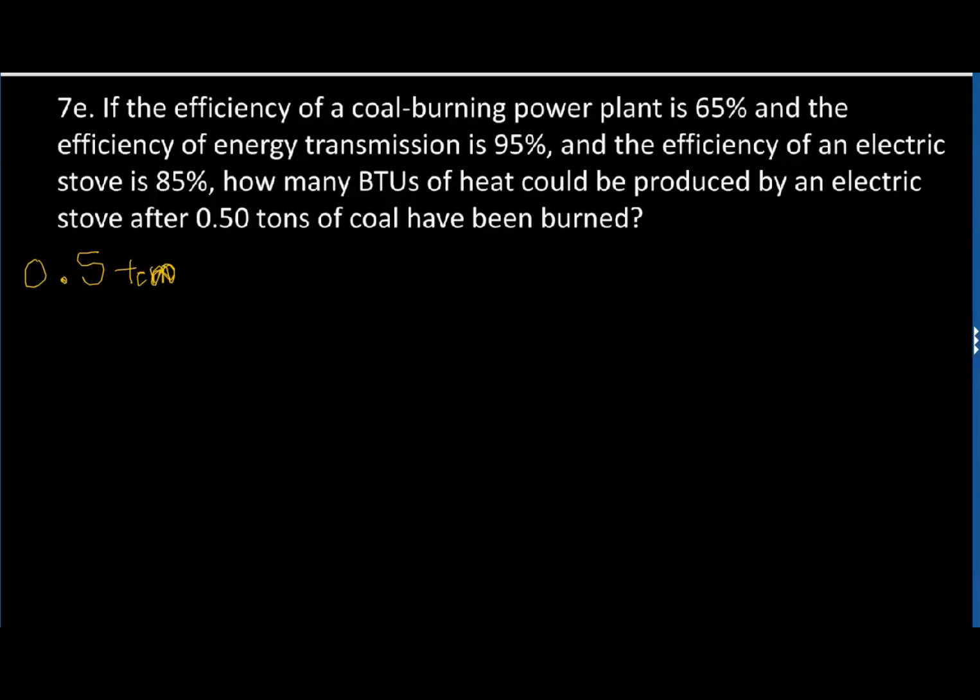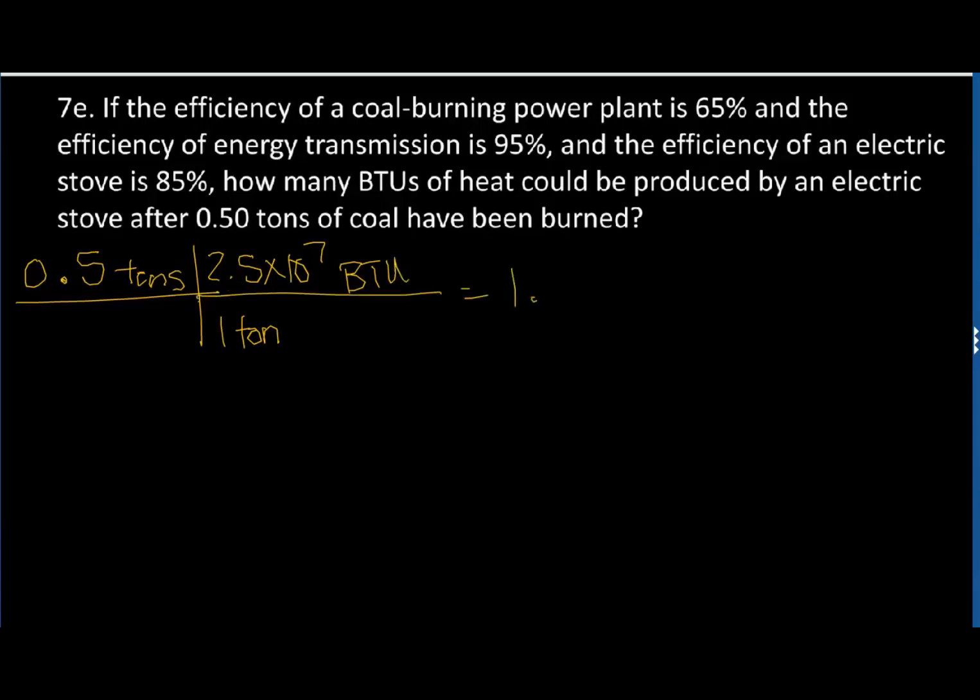I'm just going to erase this and start over. You could do your efficiency first, take all those percentages first, but I like doing it at the end. I got this conversion from that very first chart at the top of the problems page. So if it was 100% efficient, this is how many BTUs you'd have. But it's not.